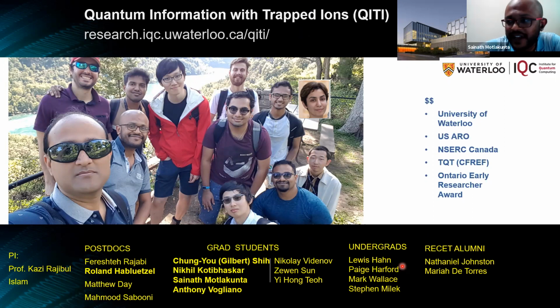So first, as you said, we are doing this long pre-bake setup where we heat these stainless steel components for about a month to reduce the dissolved hydrogen. We expect two orders of magnitude smaller background hydrogen load. And then we increase the conductance. I think people did not work so hard to optimize the conductance from the pumps.